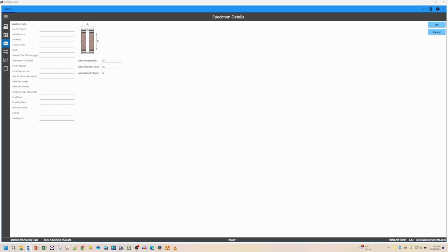The primary goal is to apply both vertical and torsional forces to the specimen, which simulates real-world shear forces more accurately than other methods. The combination of these forces produces more realistic results, making the hollow cylinder test preferable for applications requiring high fidelity soil behaviour modelling.